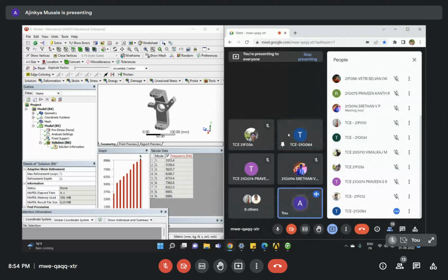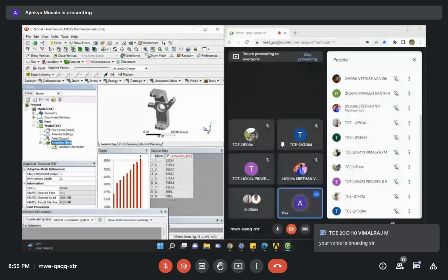No, not like that. Why we have only got 9 is because remember we have specified the range starting from 2500 to 10,000. And if you see over here, my ninth mode is at 8,986. My 10th mode is actually crossing the limit of 10,000. Got it? That's why I'm not able to catch the 10th mode over here, because it is crossing my range.